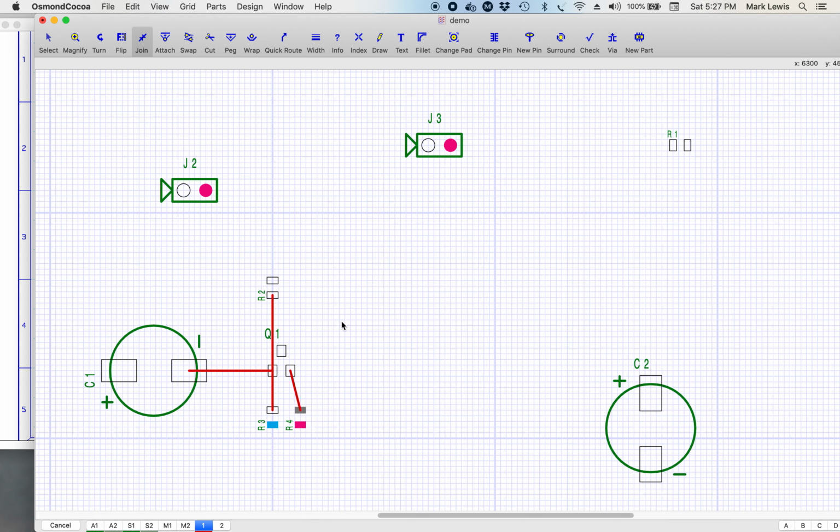It might go from one price to triple the price or 4 times the price. I don't know the exact amount, but what we want to do is just use the second layer of this board as a ground plane. In other words, I'm going to go to that second layer. I can click on it here, or I can hit the number 2 on my keyboard, and we're now on layer 2. In this case, that's going to be the bottom side of the circuit board.